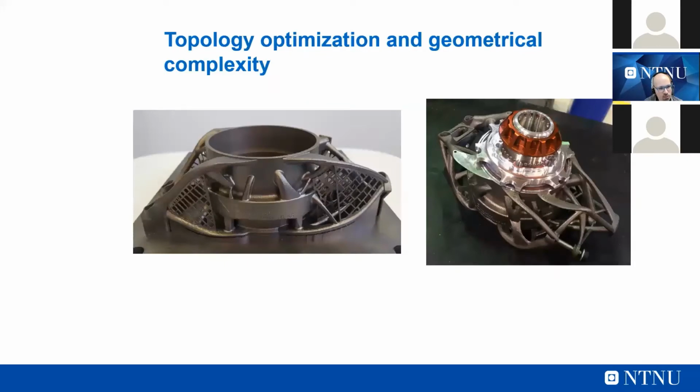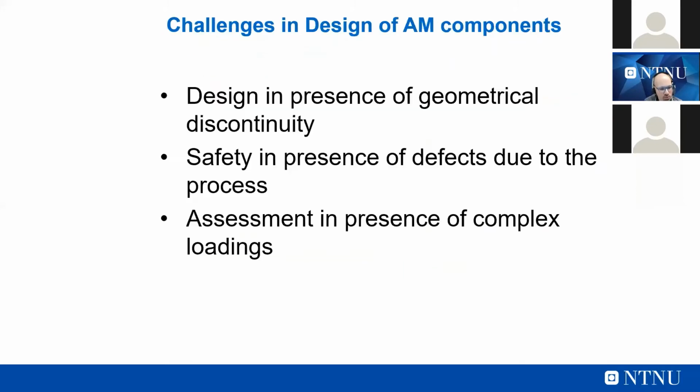Dealing with the introduction, what is very important is that an additively manufactured component has a complexity that is increased a lot with respect to traditional components. One of the main problems is that if you apply tensile loading to the component, locally you always have a triaxial state of stress present on the geometrical features of the component. On the other side, you have the defects due to the process that interact with this complex geometry. And this makes it difficult to really design against fatigue components printed by additive processes.